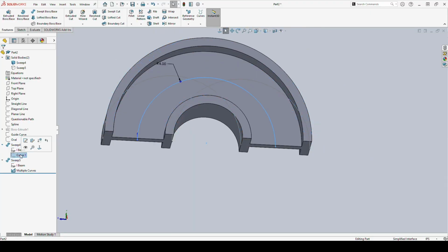There we go. And now we're seeing that this is the sketch line that I followed. And you notice it starts in the middle, and it is always the middle of the I-beam. So where you draw your sketch in this case, where that path line is, matters, because it's always going to stay consistent for this.